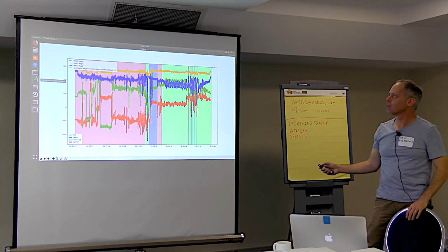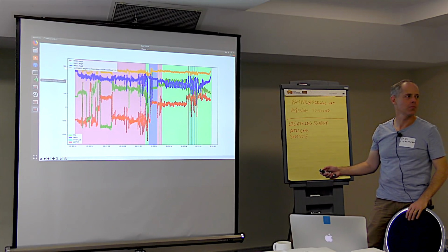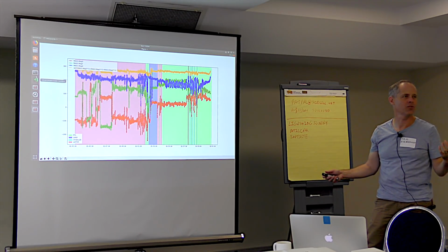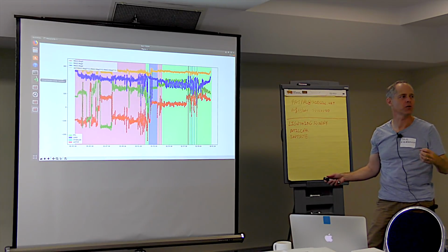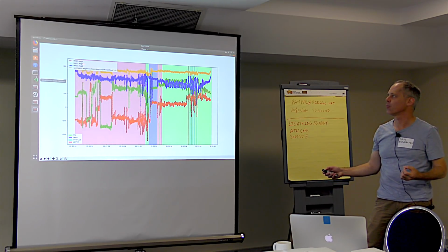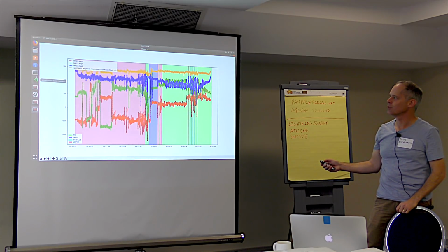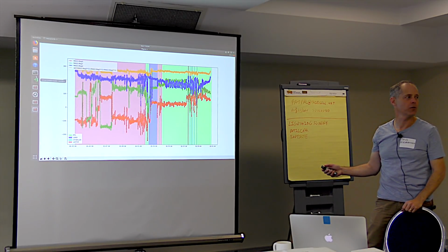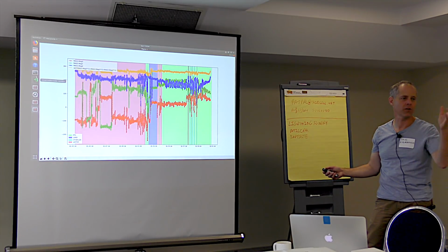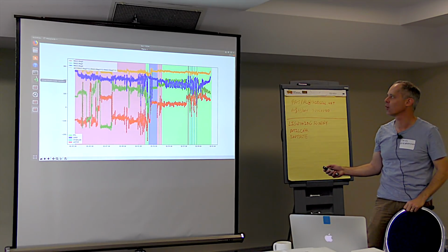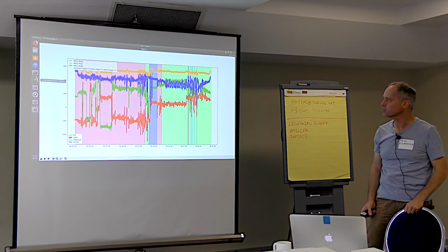So that's one of the first checks to do. If you're trying to work out, do I have a problem with my calibration, or do I have a problem with my magnetic interference from the motors? Just plot the magnitude of the field strength, and we've got those combined plots available also in Map Explorer.